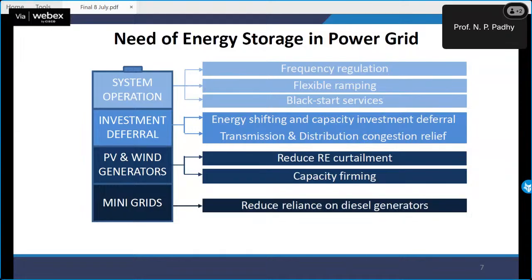So during that off-peak period, the PV energy connected to the system needs to be derated because my requirement is not there. So instead of 100, I have to derate to 65 or 70. I think this is a very, very unfortunate scenario where the renewable energy is available to me, but I'm not going to extract it because there is no taker for me. And that is where the battery could have acted as a load and got charged. So that is one interesting thing.